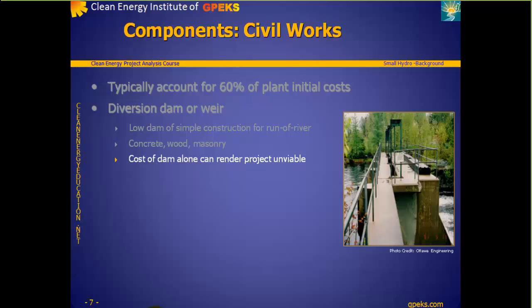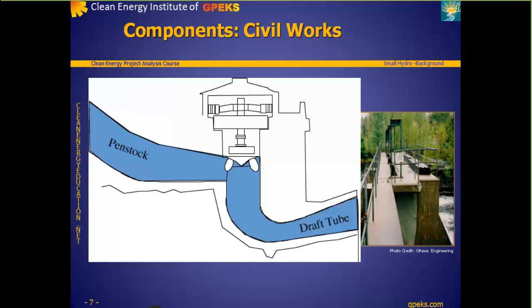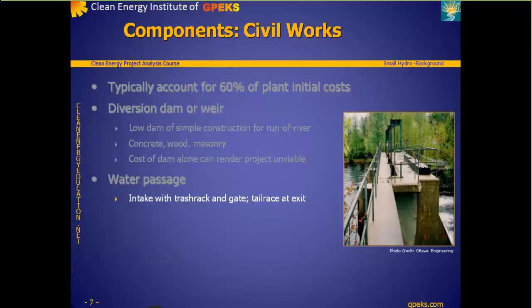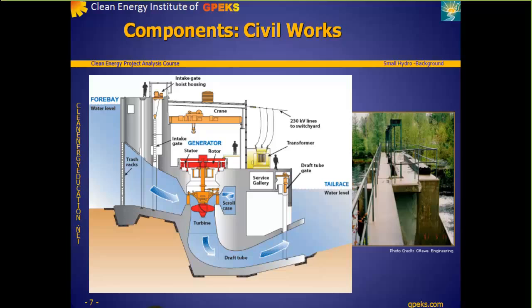The nature of the water passage will depend on the proximity of the intake and the powerhouse and what is found between them. It may be an excavated open canal, a tunnel blasted or bored through the ground, or a penstock, a pipe capable of conveying water under pressure. The path of the water passage may deviate significantly from that of the river, especially when this increases the head of the project. Sometimes the powerhouse is located right below the intake and no passage is necessary.